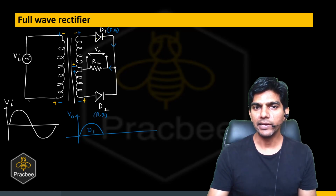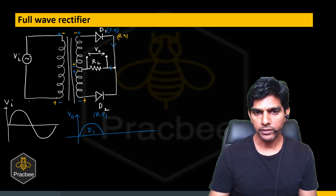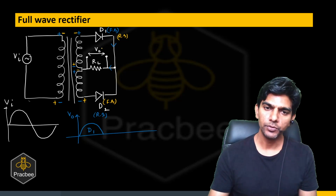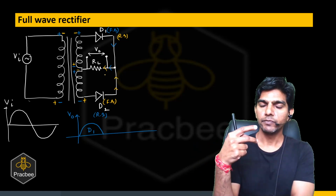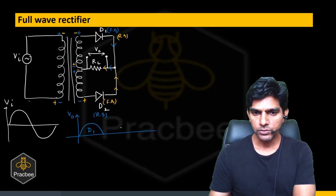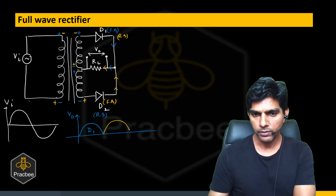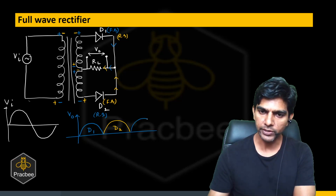Can you say now the diode D1 is reverse biased and the diode D2 is forward biased? Now when diode D2 is forward biased, it becomes conducting and D1 becomes non-conducting. So now the current will flow like this. Can you see even in the second half cycle, the direction of the current is the same through the resistor. So we'll get this output, and this output is because of D2. Similarly, for the next half cycle, we'll again be able to rectify.